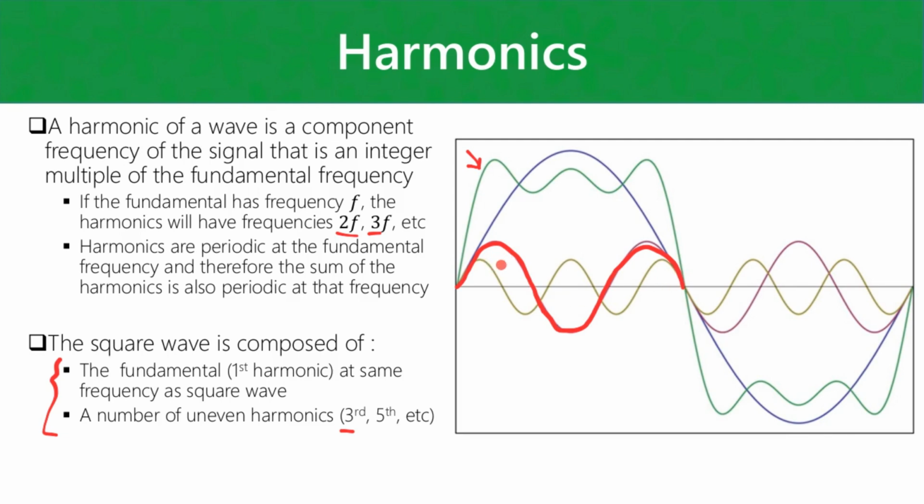So if we take a look in one half wave of the fundamental, you're going to have 3 half waves for the third. Or if you look over the whole cycle, so for one waveform, you're going to have 3 waveforms for the third harmonic. And you can see the same thing with the fifth as well. So the fifth is then going to be the smaller one.